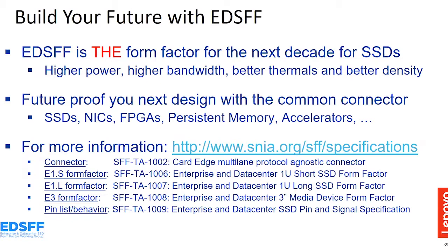And then the key point here is also, it's not even just SSD, it's even past that. It's actually something that can grow, because it's a PCIe interface to this connector and to this backplane that we can plug in the front. You can make SSDs with it. Certainly, that's the first application, the NVMe drive. But you can also make NICs. You can put FPGA accelerators, persistent memory, other different types of accelerator. There's a lot of different applications where we see this growing and allowing for a lot of flexibility. This common connector and a set of form factors that allows for these different use cases.